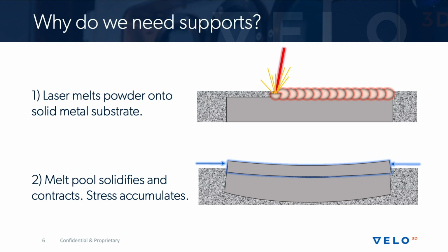Obviously, when you melt parts it's much more complicated than this. You have a couple general scenarios where you have this same effect accumulating throughout a large volume, and that will result in levels of residual stress throughout the entire volume of the part, and global gross distortions across the part. You also have this happening very locally. So on things like sensitive skins, on low angle down-facing surfaces, this can be pretty catastrophic.